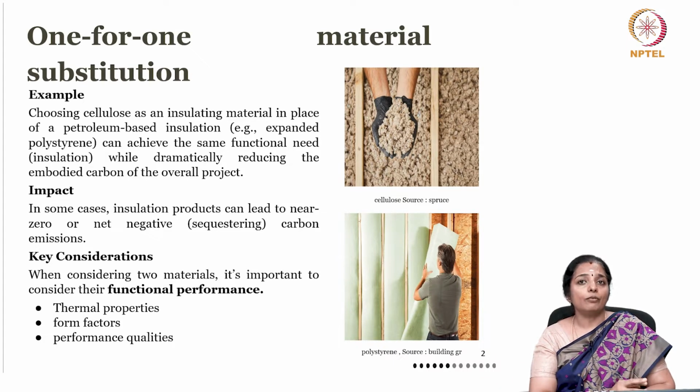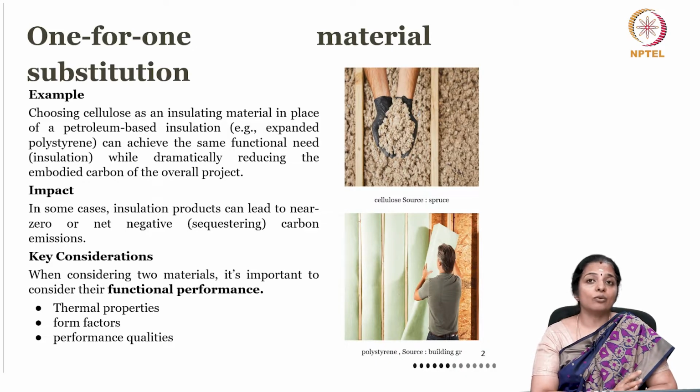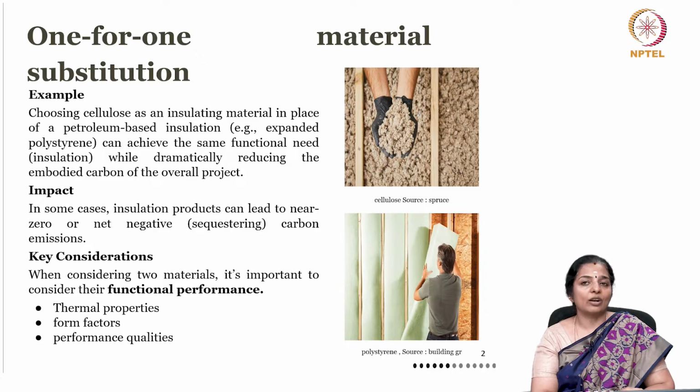Whereas, if you have carpet tiles, then it can result in 1 to 5% installation waste as against 10 to 20% installation waste in the broadloom carpets. And the useful life of the floor can also be extended with selective tile by tile replacement for damaged sections.